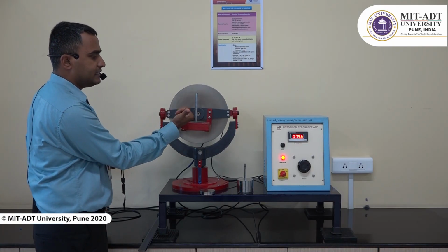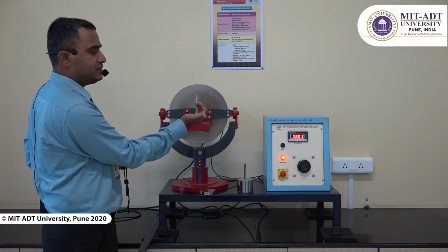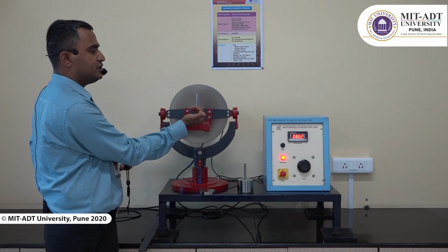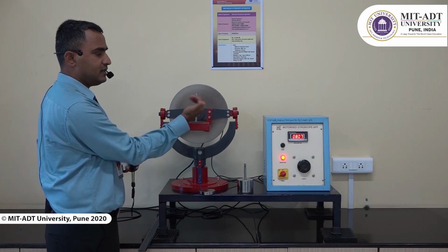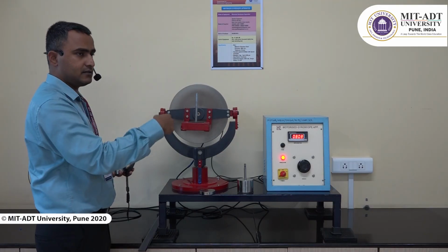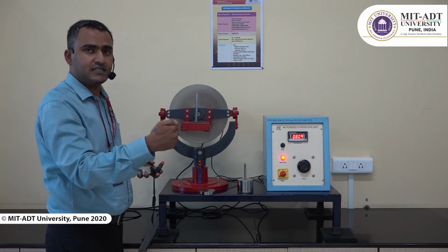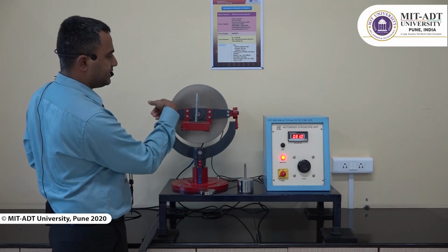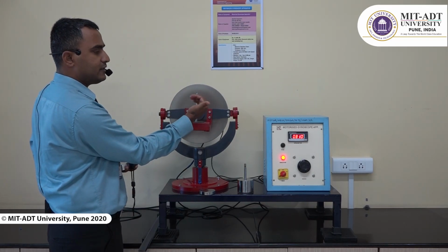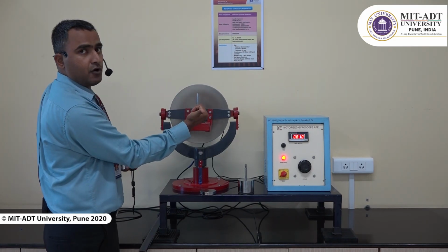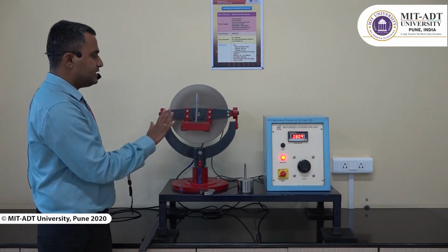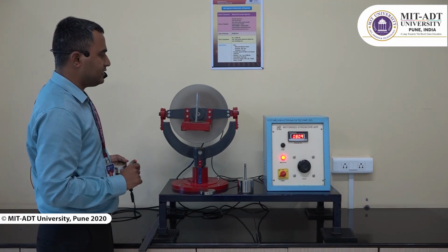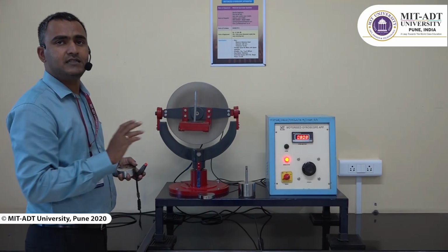With this RPM, we just need to understand the axis of spin of the disk. We will make use of the right hand to denote where the axis of spin position would be. If I use these fingers in the direction of rotation of the disk, which from the observer side is rotating anti-clockwise, I will use the fingers in anti-clockwise sense. The thumb of the right hand will indicate the position of the axis of spin. So this is the axis of spin. We will ensure that we get the stabilized position where the axis of spin remains in horizontal position.